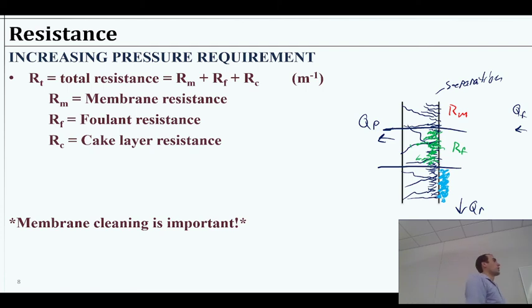For membrane operation, it's a little different than granular filtration. In granular filtration, we often had systems where we would take it down for 20 minutes at a time or more to physically push all these particles out and away. For membranes, sometimes we backwash, but it's a lot more frequent typically, where we'll be operating, and we'll take 20 seconds to push clean water backwards through it and try to push off some of this cake layer.